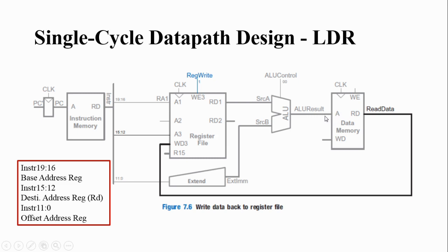So what will happen? From the data stored in the corresponding address which is given here will be read out through this. Say if the address is 000001, whatever data is stored in that 00001, that content will be sent out or read out through this RD.